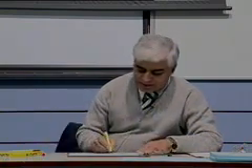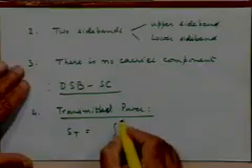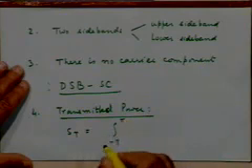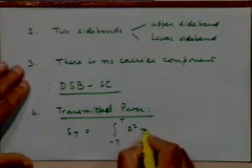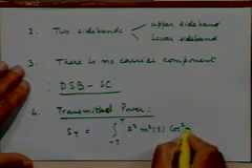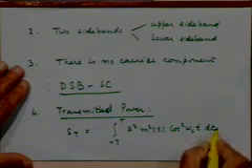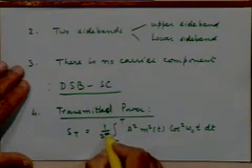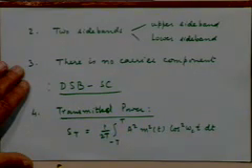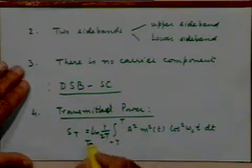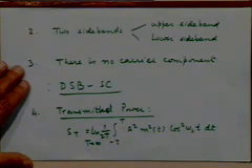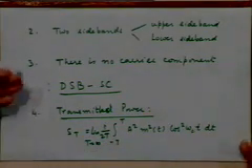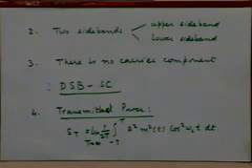But in general your message waveform may not be periodic, so we can't talk about a period. But if it is not a periodic waveform, you can always do this. Let's say from minus T to plus T, the integral of m square t cosine square omega ct dt. This will be the energy of the waveform in the interval from minus T to plus T. So divided by 2T, and what should you do? Take the limit as T tends to infinity. That will be the definition of our calculation of power for an arbitrary waveform.